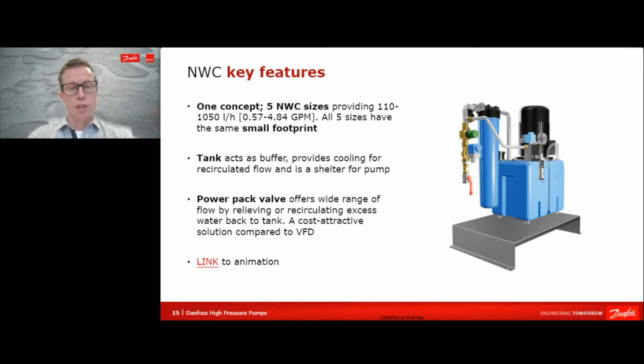It also means that these units here, they have a very long time in between service. Normally for our pumps, we are saying to make a service inspection after 8,000 hours, but as long as you have proper filtration on your unit, which we have already built in, we see that these systems can run much longer without any problems, also more than 20,000 hours.